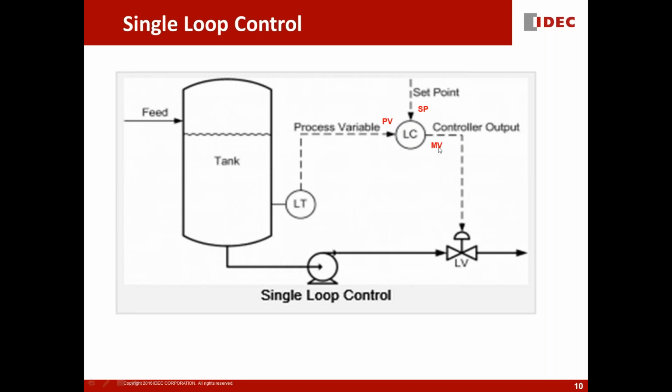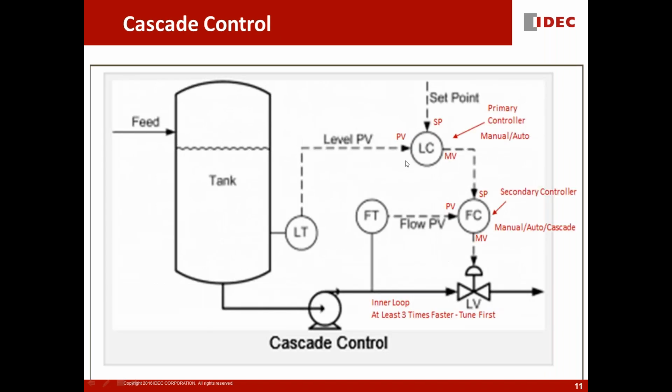And then you get the set point, and you get the manipulated variable, that's your output. So basically the PID will send an output to pump more or less liquid, water, or whatever it is, to maintain the desired pressure in that tank. If you have more usage of that tank, of course, the PID is sending more flow into that tank to maintain pressure. That's all it is.